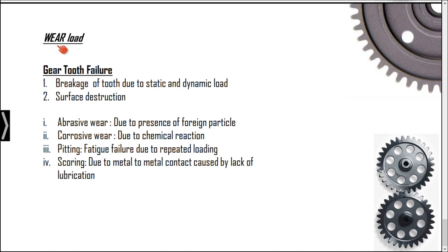In order to reduce the wear on the gear, it has to be surface treated. That is also one of the important parameters we have to consider, because surface hardness is a very deciding parameter when we talk about wear. So surface hardness also needs to be considered while we design the tooth based upon the wear load.